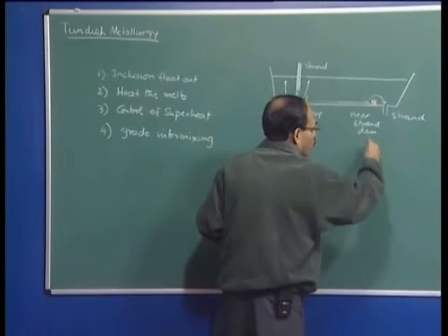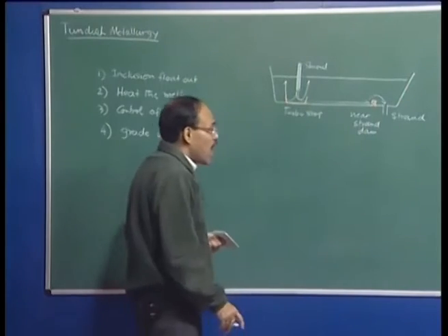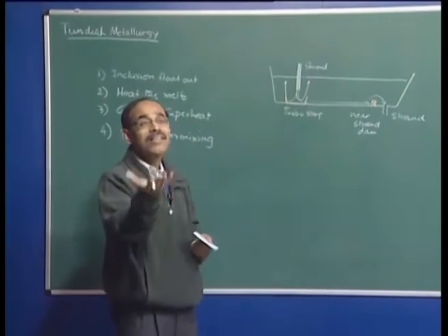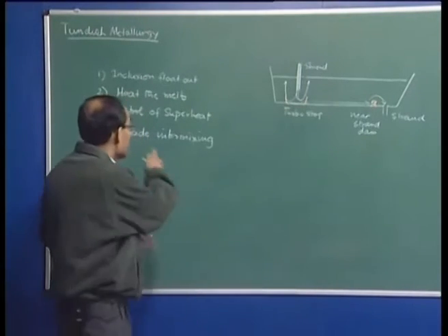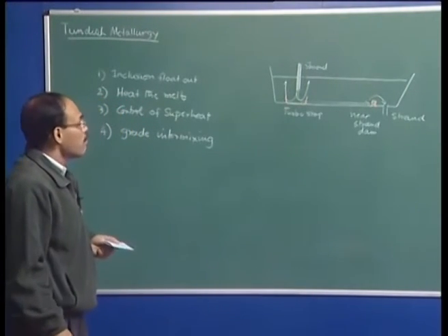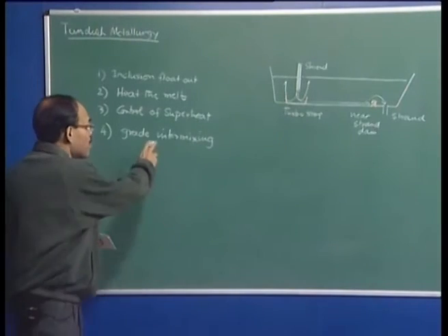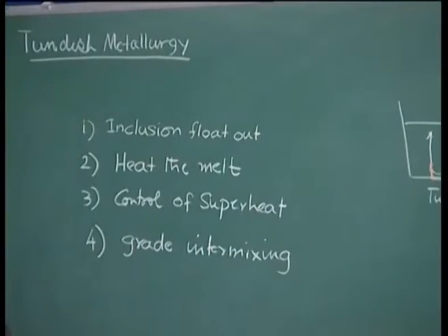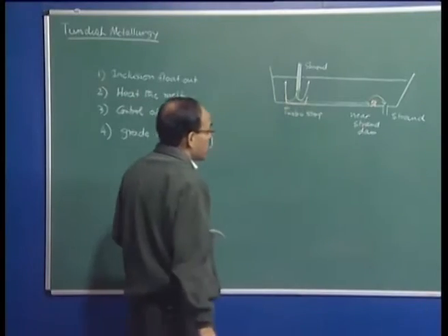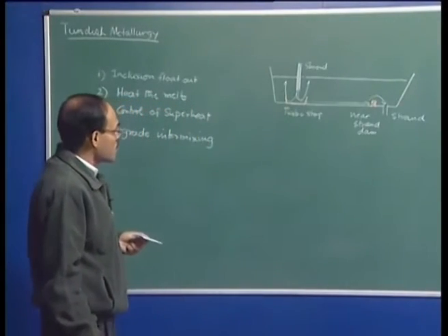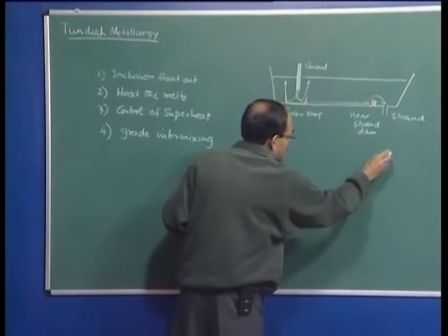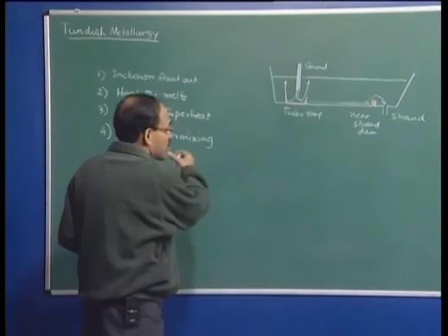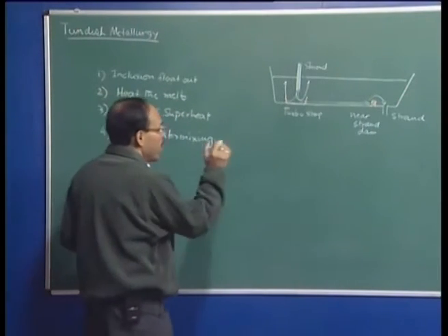will form billets or blooms or slabs which are going to have composition neither of the previous grade nor of the former grade, but an intermixed grade, and that is why grade intermixing is a very important aspect, because intermixed slab, bloom or billet are often downgraded. So, therefore, to economize the performance or to improve the performance of the cast shop, we want to have as low a transition slab volume or mixed slab volume or mixed bloom volume as possible.